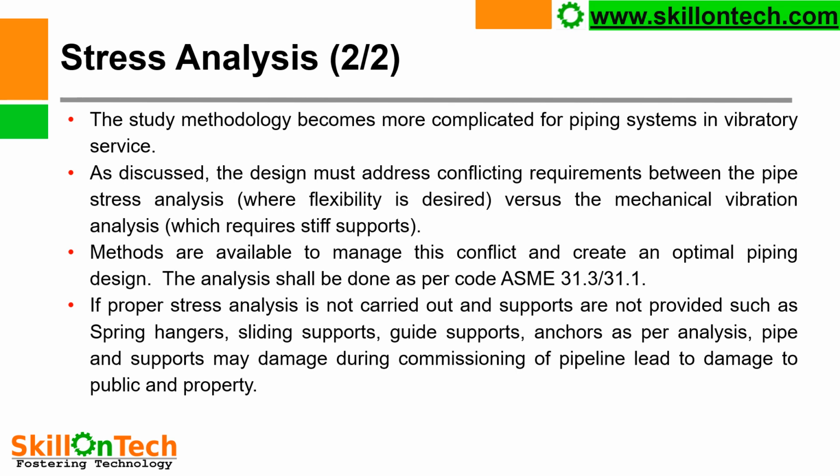If proper stress analysis is not carried out and supports are not provided, such as spring anchors, sliding supports, guide supports, anchors, as per analysis, pipe and supports may be damaged during commissioning of the pipeline, leading to damage to the public and property.